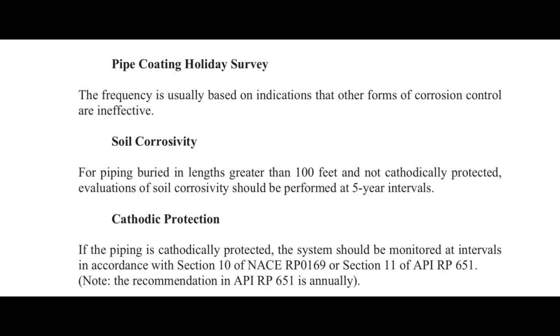Pipe coating holiday survey. The frequency is usually based on indications that other forms of corrosion control are ineffective. Next, soil corrosivity survey. For piping buried in length greater than 100 feet and not cathodically protected, evaluations of soil corrosivity should be performed at 5 year intervals. This is as per API 570. Sometimes the standards related to some clients, meaning some companies, will be different.